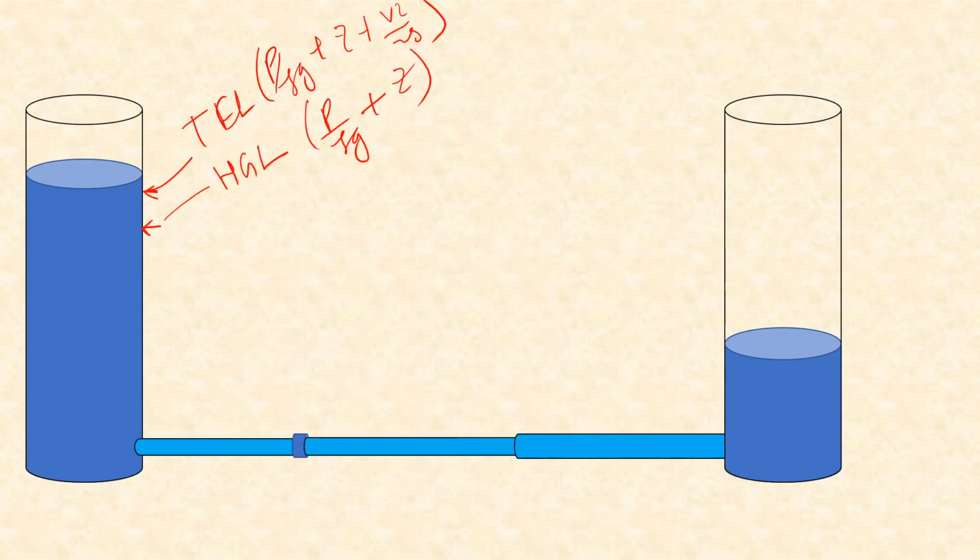So we'll start drawing here, and it will keep decreasing along the length of the pipe, and at this joint there will be some minor loss because suppose it's a not very well designed and rough kind of joint, so some energy will be lost here. We can show that by this kind of sudden drop in head. Then again it will keep coming like this. Again at this enlargement or expansion, some more head will be lost,